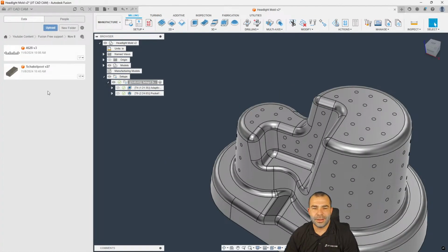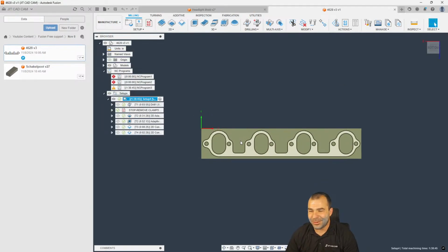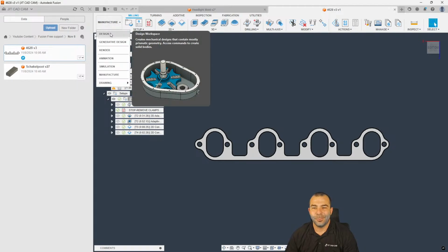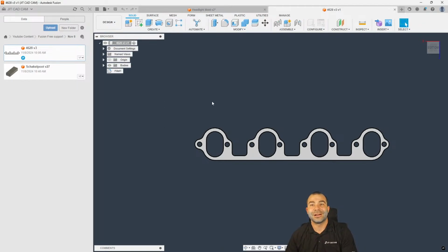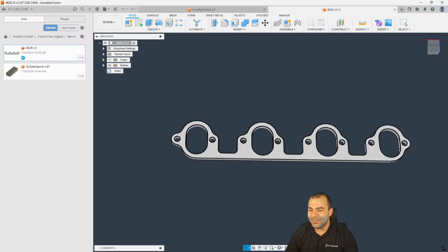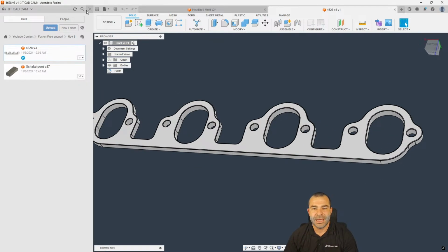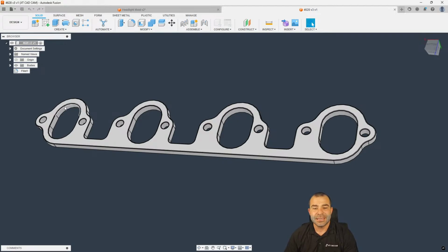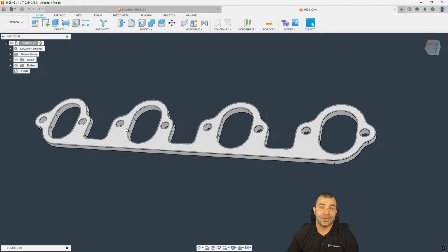So one of the first questions that I encountered came from a very good friend of mine, and he is one of my customers nonetheless, Wes Collins. He works for Neighborhood Brake Center and makes headers for anything and everything, I think, at the end of the day. But what he was curious about is on his part, he has this lovely header flange, that the size of the actual exhaust tubing on this flange needs to be modified. These actually are much too large of ports, or in this case, the actual oval piping that he's going to put in. These are 2.25 ports, and he wants to do the 1.875 ports.